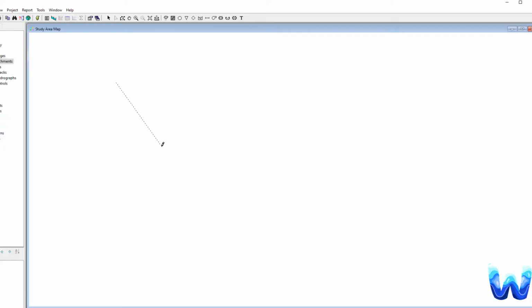You have to export those hydrographs, turn it into spreadsheet form, and now we have to find a way to input it into a software that can do accurate hydraulic calculations. This example, we're going to select EPA-SWMM. So now we have to build out our EPA-SWMM network, matching our project that we did in WWHM 2012 using junctions, conduit elements, and so on. But there's no data for it. So what we have to do is export that data from WWHM 2012, bring it into EPA-SWMM, which is a confusing process on its own.